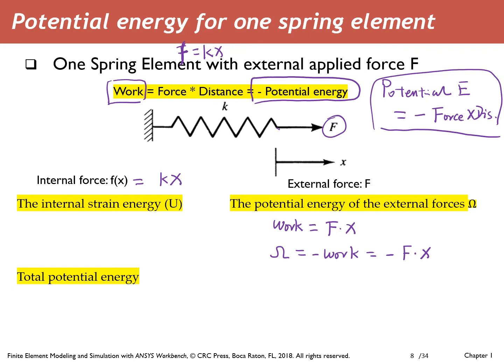Instead, we need to use calculus. That means every time we calculate the work, we do it locally, in infinitesimal deformation. We generate a small deformation by this force, and when the deformation is very, very small, we can assume the force is constant. That gives a small work by the small deformation and the internal force.